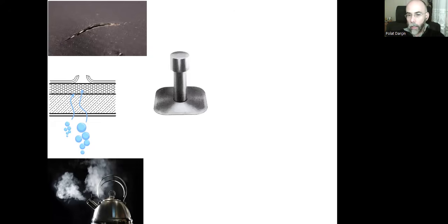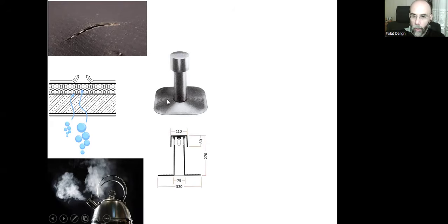We don't want this. So for the flat roofs, we can place these tiny air chimneys that, I don't know what they are called exactly, but it has this section. We can place these underneath the water insulation, and we can have a hole in the water insulation so that this towering part can be placed inside this hole.